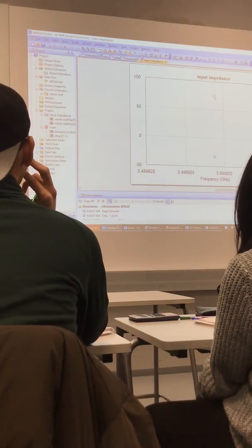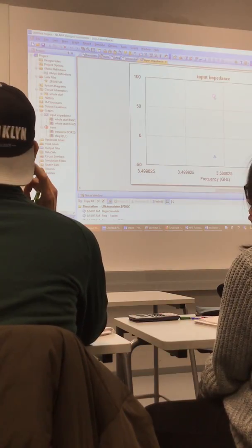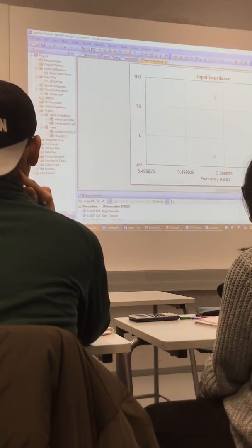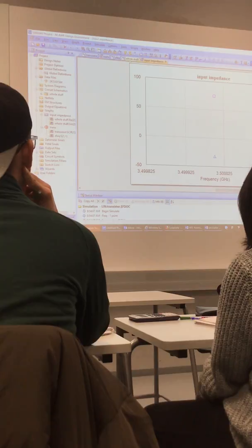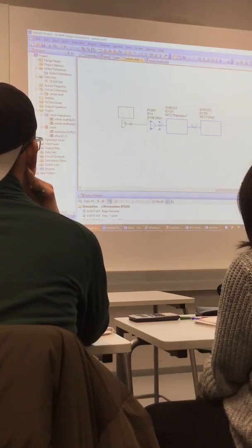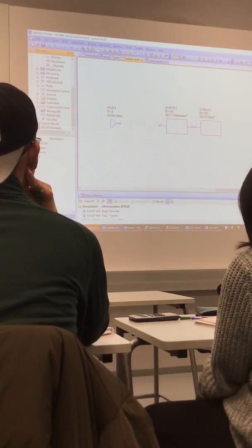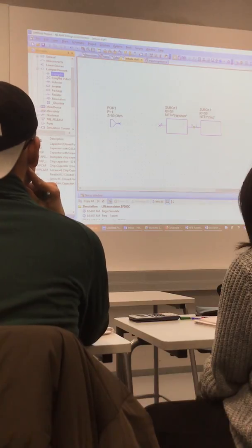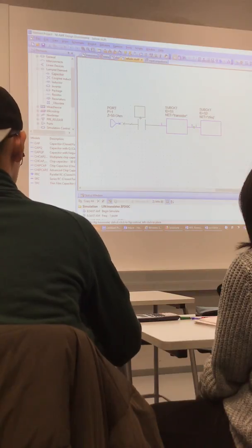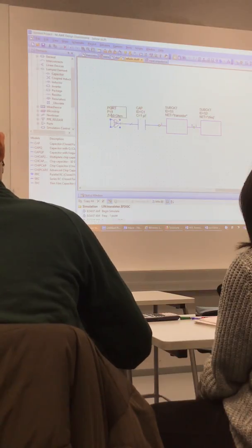Now the imaginary part of the input impedance is positive, isn't it? It's positive. To compensate it, I have to add a negative impedance. Therefore, the component that I connect to the whole stuff, I connect it here, is a capacitor. Elements, capacitor, added, connected.